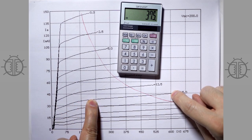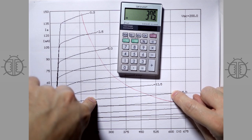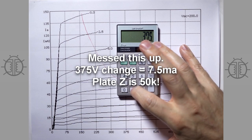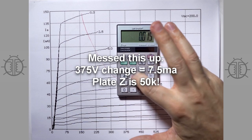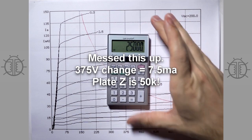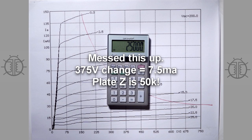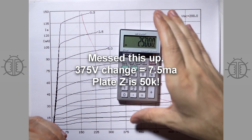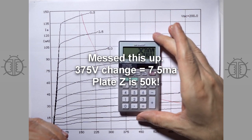So we're going to change the plate voltage by 375 volts, but to do that, we're only going to need 15 milliamps. So we'll divide this by 0.015 equals. So look, our new plate impedance is 25,000. All right, and so remember how a perfect current source would have an infinite output impedance. Well, this isn't infinity, but it's getting up there.